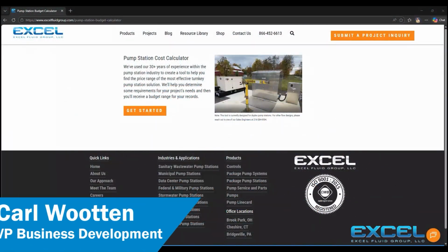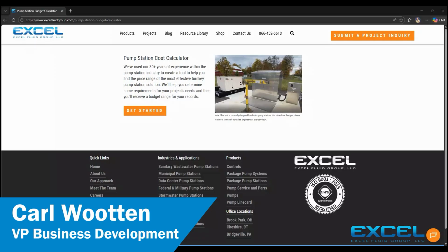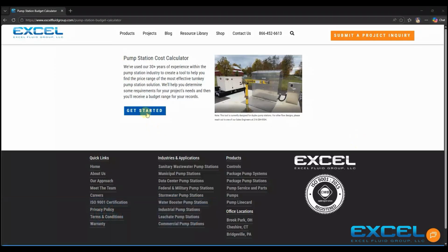This video is to give civil engineers and wastewater pump station engineers a comprehensive overview of the budget calculator for packaged pump stations. Here at XL Fluid Group, we commonly get involved with packaged pump stations ranging from under 100,000 gallons per day up to 10 million gallons per day. This tool's current range is designed for under 100,000 gallons per day and is currently limited to 2.25 million gallons per day flow capacity, but there will be future revisions coming.